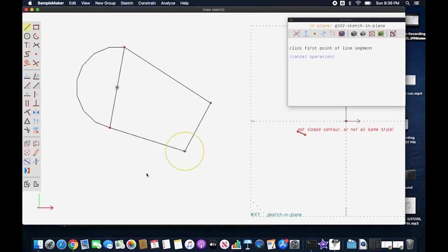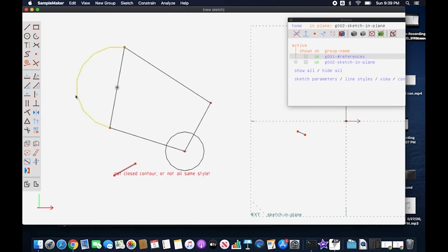And then I'm going to show a lot of times too, if I'm drawing, I think you remember before we used the datum point to find points that we may not have. So here I'm going to draw a datum point somewhere, and I want that datum point to be on the circle. So I'll select the datum point, I'll select the circle and hit on, and now I can click and drag that anywhere I want.